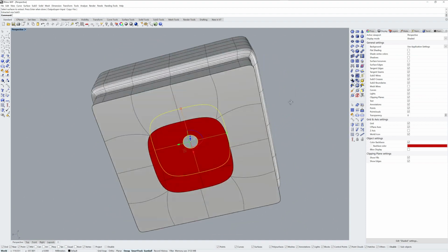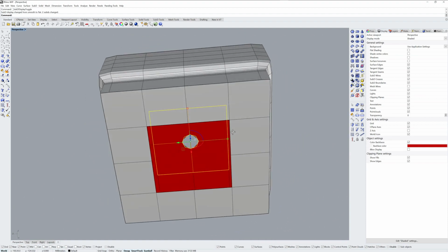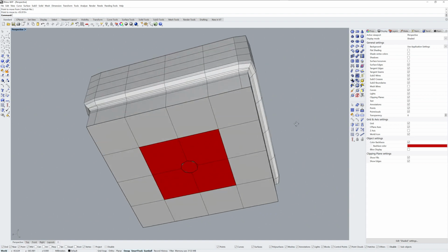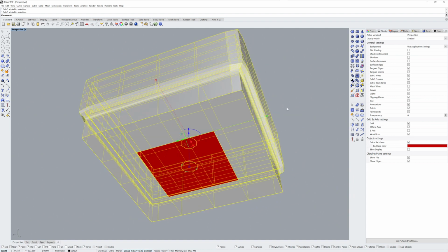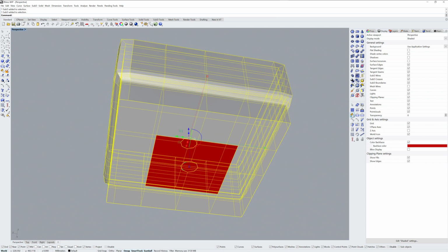Okay, I'm going to toggle into flat mode here, so tab, and then I'm going to use the move command, M enter, and move from that vert to there. And then I'm going to select this and this, so shift is held down when I make the second selection. And I'll use join.